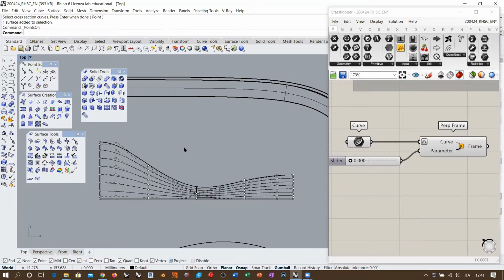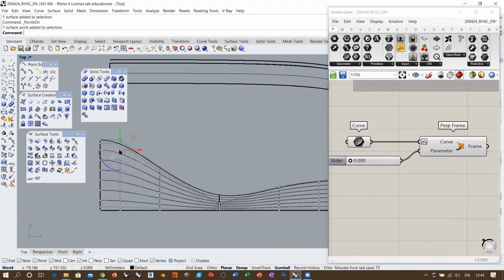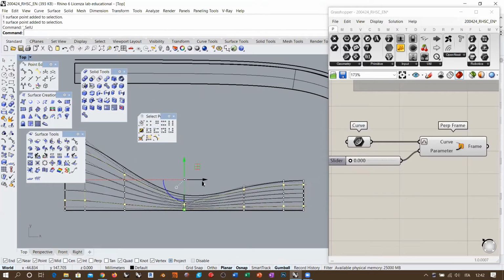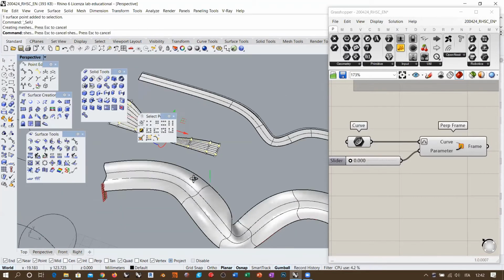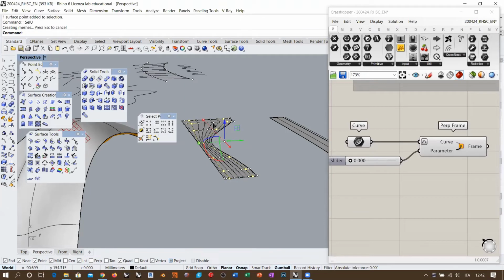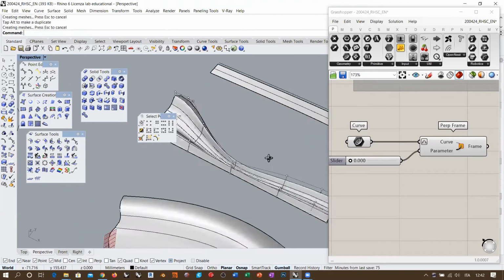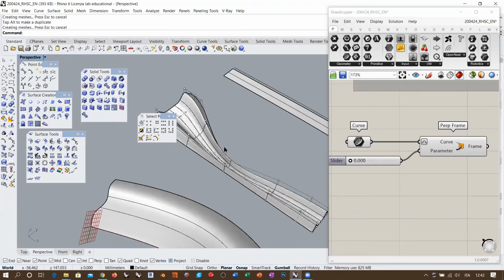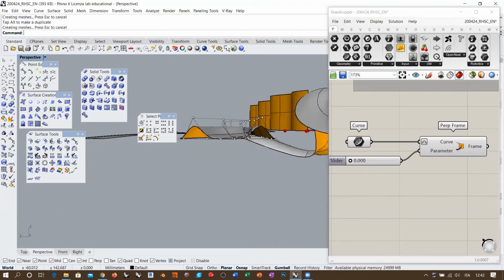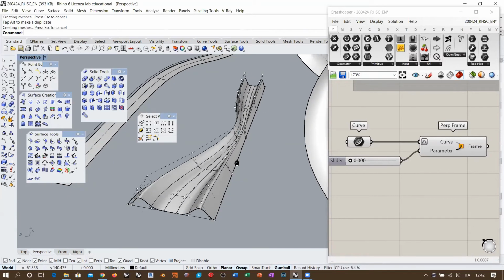Okay, by needing it means that if I get to these results, it is eventually because I want to activate the control points, and I don't know, I want to take this line of control points and this line of control points and leave all the rest untouched. And so once I select these 2 points here, I can go into selection and point selection and select, for example, all the points in the U direction. Okay, so I select all the point lines. And then I go, for example, here in perspective, and I create this rebuild because I wanted to do something like this.